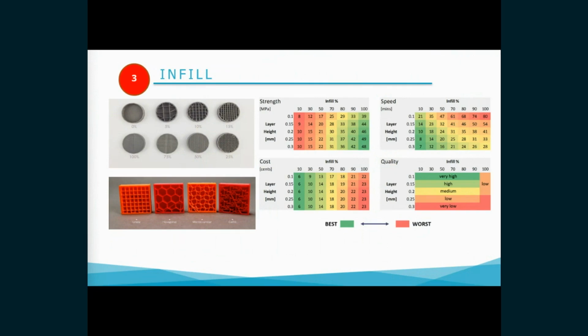Ranging from a simple line to more complex geometric shapes, infill patterns can affect a part's strength, weight, print time, and even its flexibility. There are many different types of 3D printer infill, like linear, honeycomb, grid, triangles, cat fill, hexagon, etc. In most cases, an infill density between 20 and 50% is ideal. Less than 20% results in flimsy parts, whereas more than 50% begins to take too much print time and use more material.